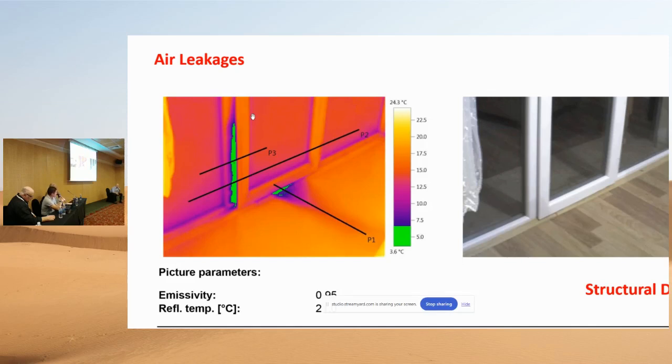No, but I mean on the scale, because we do that kind of project where we do 200 houses, then we do an airtightness test. Complete areas. We do really accurate measuring with point clouds, then prefabricated walls and roofs, and make an envelope of the existing buildings. So we do this kind of depth analysis: an airtightness test, big point clouds, construction tests, pulling tests. That's a really good solution for, let's say, 200 houses at least.